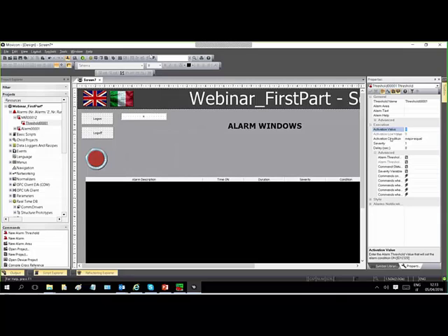If you have the same name between variable and alarm, you don't need to associate because there is an automatic association. So just a new button, and I toggle the bit in this way. Why not write a description? It takes the threshold description, so it could be important to set a correct description name.